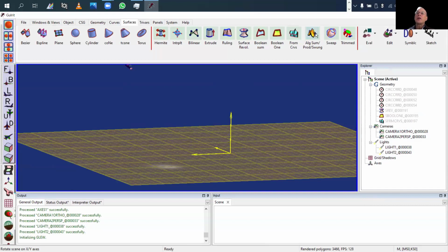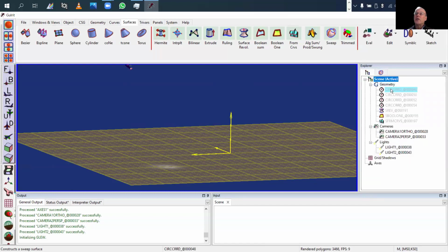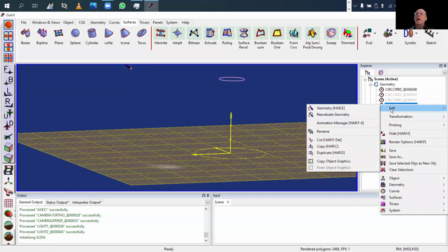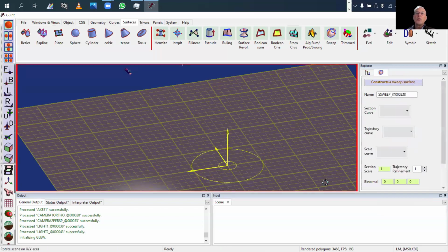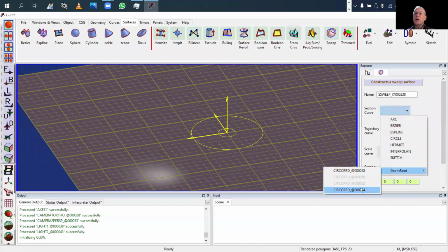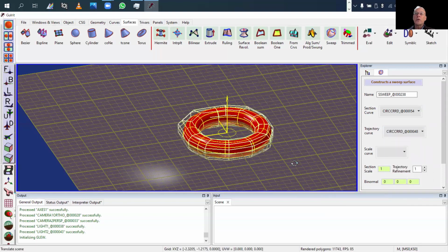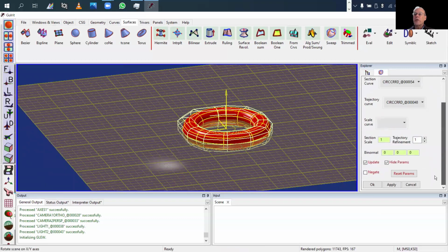There are more advanced shapes here. A constructor, I'm going to skip it. Sweep allows you to take a section like a circle. Maybe we should try it. Let's take this circle, but again, I'm going to reset its Z. So again, I do something that I didn't do earlier. Edit geometry. Edit geometry takes you back to the constructor, and then I'm going to reset the Z value to 0. So now it's at the beginning. I'm going to make it even smaller. So basically, I have 2 circles. The cross section is going to be the smaller circle, this one. The trajectory curve is going to be the bigger circle, and you can guess I'm going to get a torus out of this. In fact, I can also apply a scaling along the sweep and so on and so forth. That's another constructor.